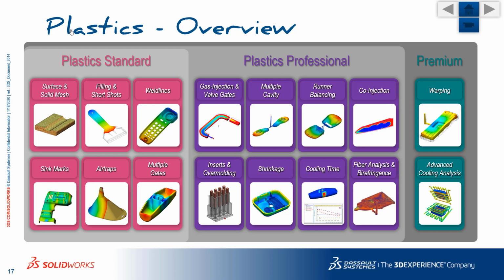And then premium takes it to another level by understanding cooling and warpage. Here you're going to actually get not just warpage predictors, but actual results. How much does this part warp? There's warpage predictors in plastics standard and in plastics professional, but they're just predictors and indicators. Here in premium, you get actual results, so you know how much warpage happens to the millimeter. And then you get advanced cooling, so you can understand the cooling channel design through the mold and how it affects the cooling of the part. So that's plastics.